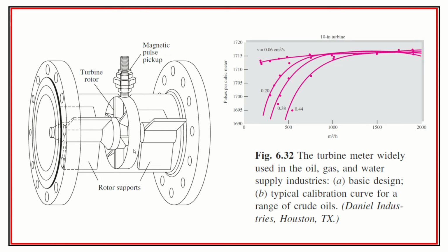Here's some flow meters. I have a lot of experience with this one right here, where you have this rotating vane inside here, and this is a very, very common type of flow meter. There's a little metal nub on this rotating turbine here, and there's a magnetic pulse pickup that gets the RPM, and then there's a calibration curve used on there, but this will estimate what the volumetric flow rate is.